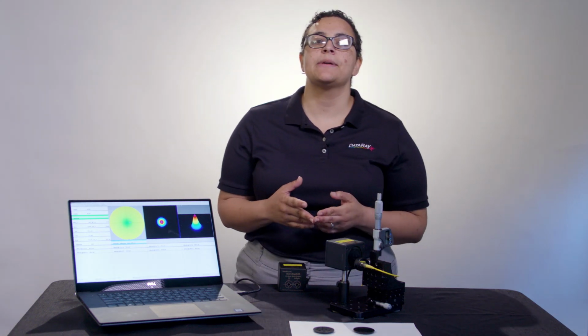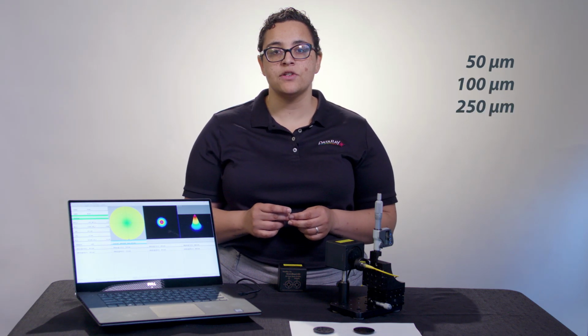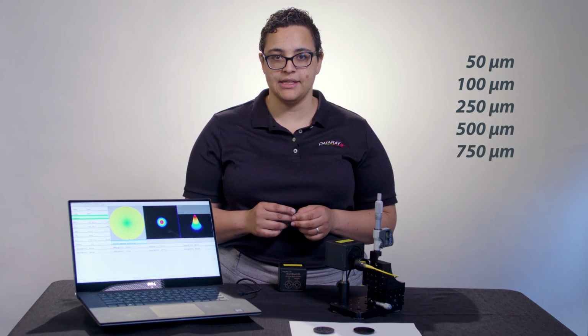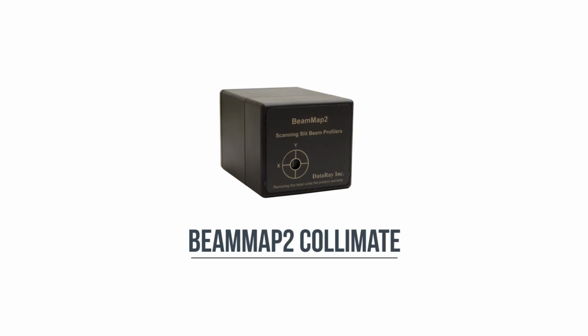Your BeamMap2 should be carefully selected, as there are many different plane spacings available for different applications. We offer 50, 100, 250, 500, or 750 micron spacings. In addition, for very well collimated beams, we offer the BeamMap2 Collimate, which has a significantly greater plane spacing of 5 millimeters. This allows for real-time, accurate divergence measurements.